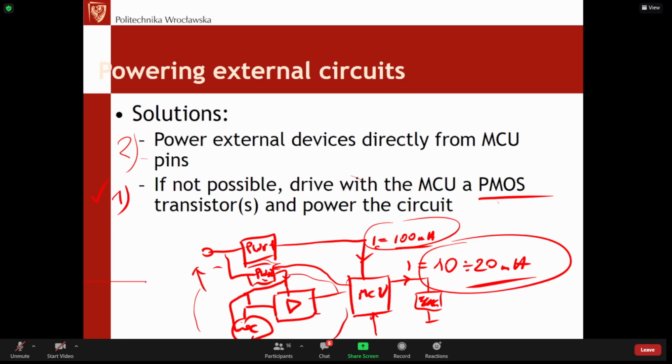during this semester, for example, where you have 7.2 volts here, and you've got 2.5 volts here, and then you use a linear regulator, or some of you wanted to use a Zener diode for this kind of circuit. In case of linear regulators, of course, there will be a huge voltage drop on the linear regulator. So 7.2 minus 2.5, which is 4.7 volts. If you multiply it by this 100 milliamps current, it gives you about half a watt power loss.